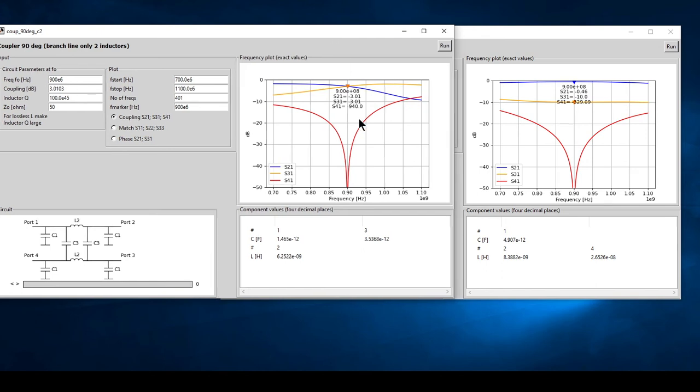characteristics of the couplers. You can see in this case the coupling doesn't really have a bandwidth which is too large. Let's also make this 10 dB coupler. Okay, so this has quite a slope on it, so your amplitude imbalance is going to be worse for this case, the two inductor case, than for the four inductor case.